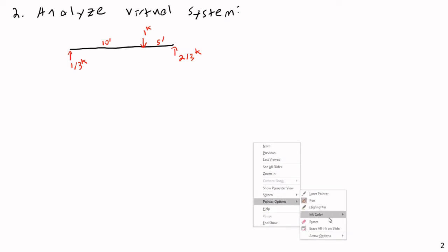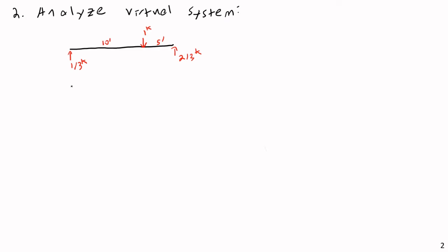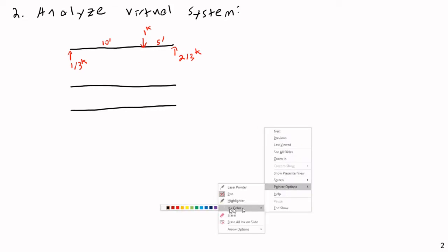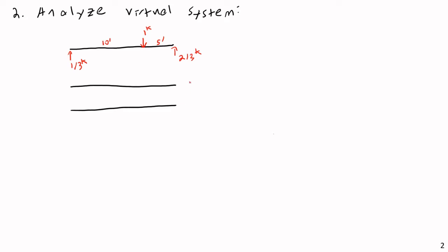So let's go ahead and get the shear diagram. And I'll go ahead and draw the beam for the moment diagram as well. So here, V in kips, and M in kip feet. Initially, and I'm just going to do these via inspection, our discontinuity is there, and so we're going to jump up to 1/3 from the initial load.